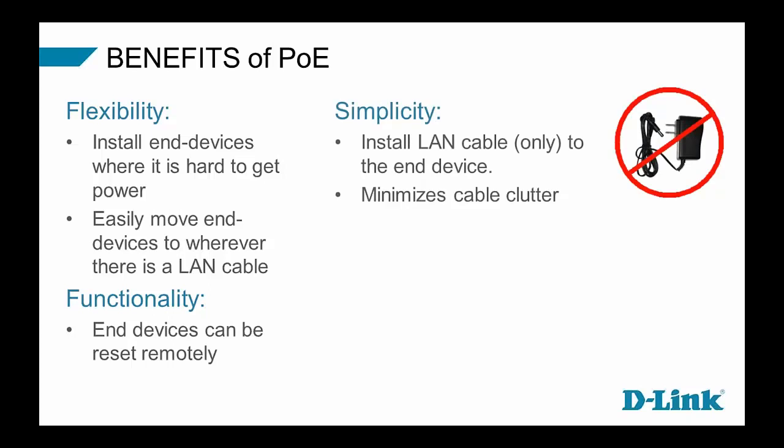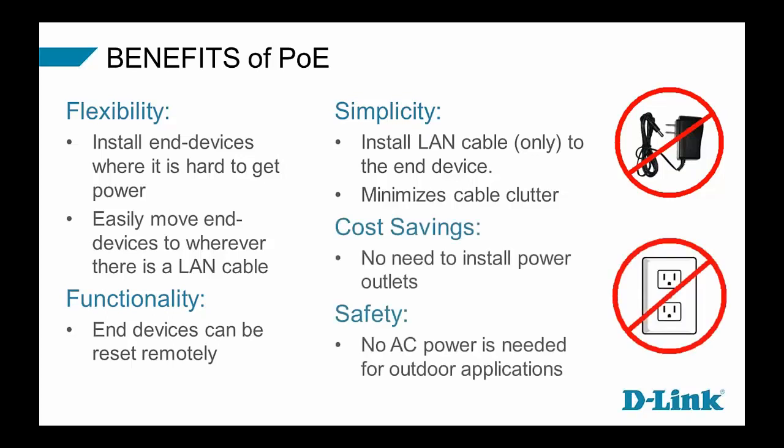PoE is really simple. Again, I mentioned this earlier. I don't need these AC to DC wall wart type of power adapters. All I need is a LAN cable, so I'm minimizing cable clutter at the same time. And then I'm saving costs. I don't have to install power drops or power outlets everywhere I want to put my devices. And especially with outdoor applications, anytime you're running AC outdoors, you have additional safety concerns.